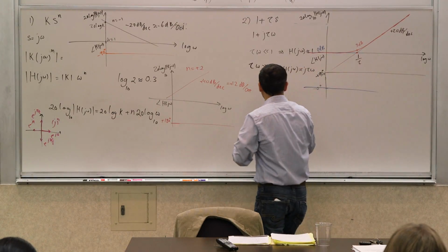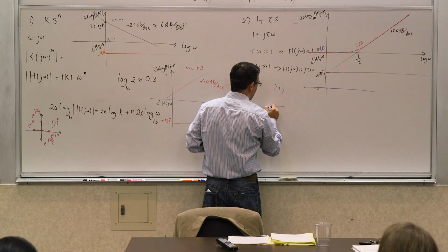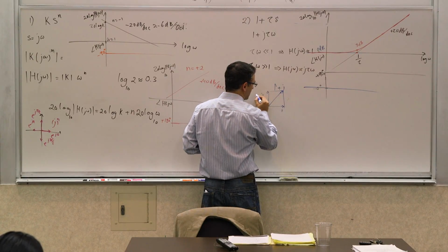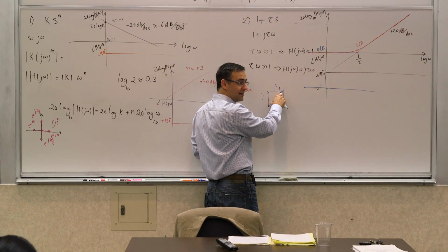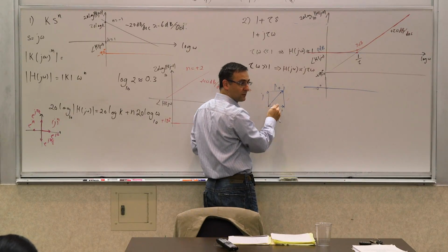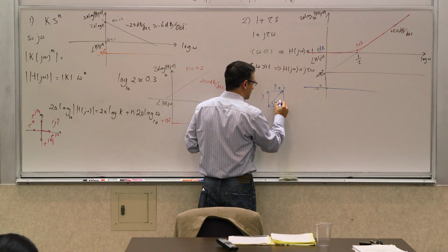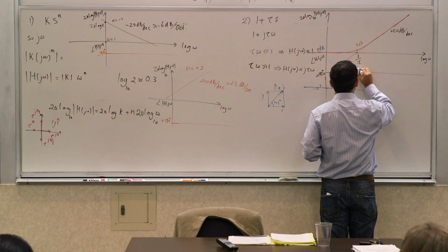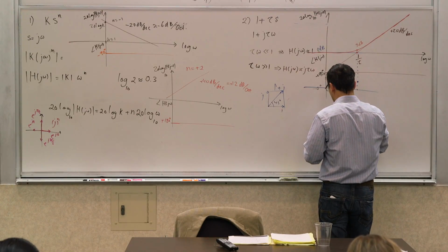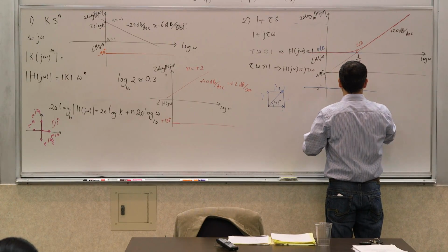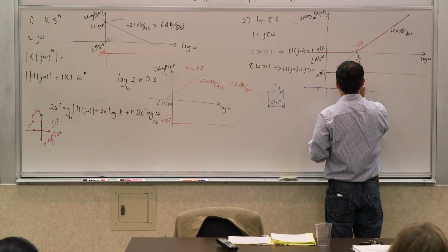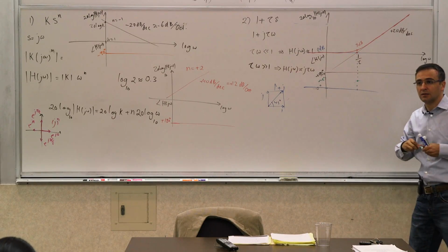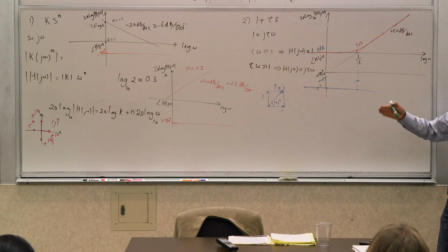If you think about it, it was 1 plus j at that frequency, so it's 2 vectors of equal magnitude. This has the magnitude of square root of 2, and this is 45 degrees. So at this frequency, I know exactly what it is. At this exact frequency, it's exactly halfway through. So my phase at this point is plus 45 degrees. So we know it transitions from 0 degrees to 90 degrees and goes through that.